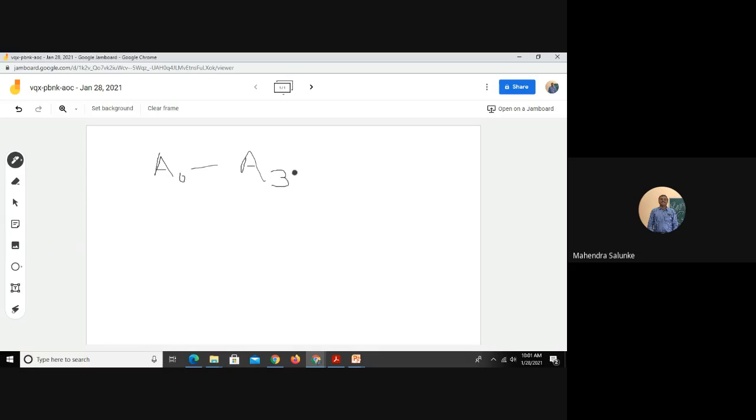These are basically the pins which are created by your memory management unit, right? So that is segment translation and page translation. After that, we get these 32 pins. Out of these, the lower 2 bits are A1 and A0. I will write in this format, A1 and A0. Now, with these 2 pins, we have 4 combinations: 0 0, then 0 1, then 1 0, and 1 1.